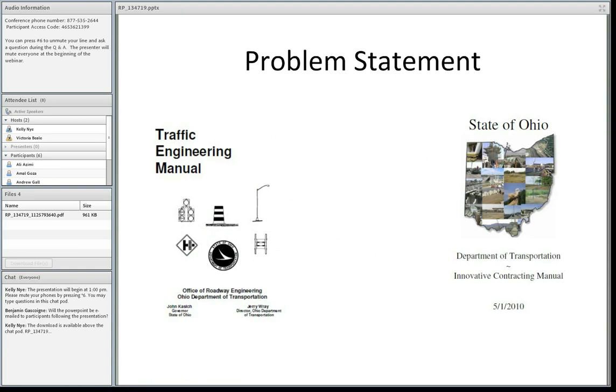The first is a traffic engineering manual. QUEWZ is identified as an appropriate piece of software to look at queue lengths occurring in work zones with lane closures. A queue length analysis is required when looking for an exemption for a proposed lane closure that violates the permitted lane closure map.